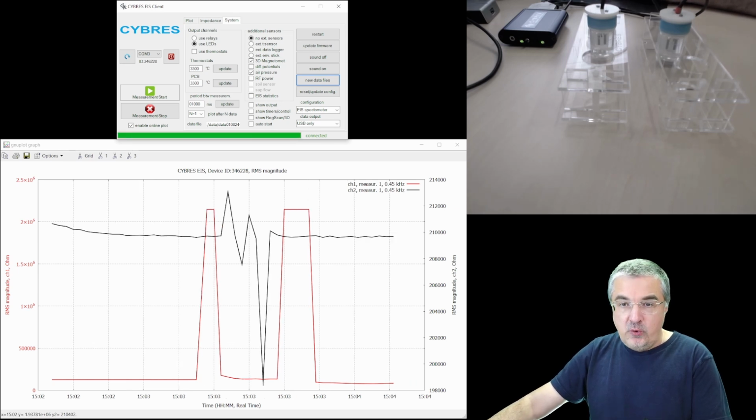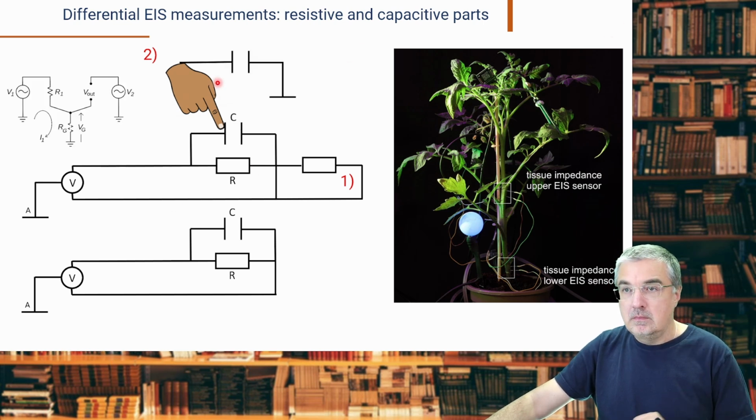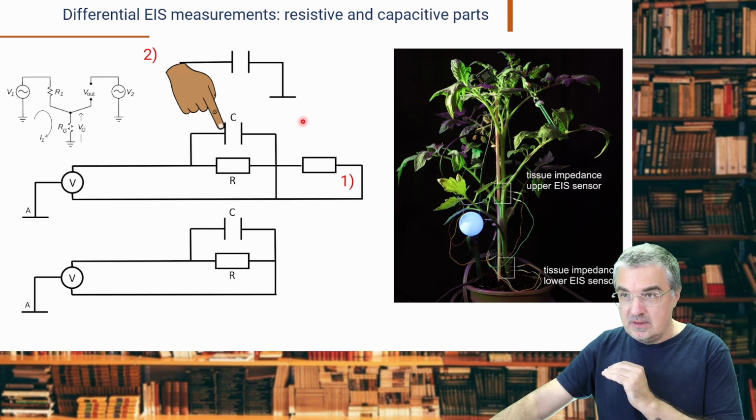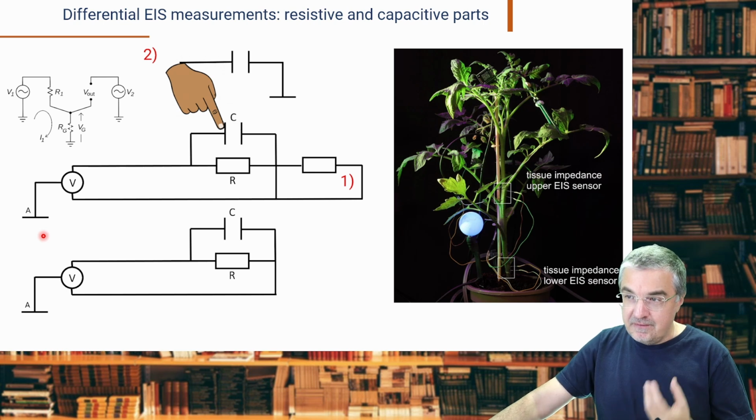So to explain what is happening here, we have the same problem like I discussed before. My body capacitance is interacting through a common ground. This virtual common ground is still interacting in a capacitive way, through alternating electric fields, with the ATX power supply, and is interacting again with the analog ground of this measurement device. It sounds a little bit crazy, but this is the way electric fields appear or work in the setup.